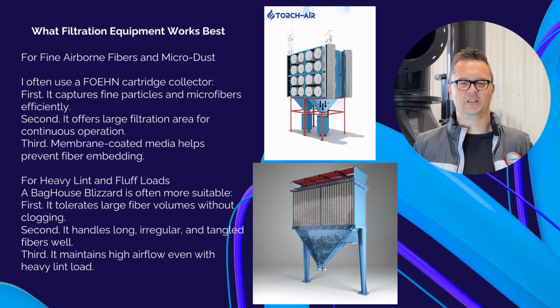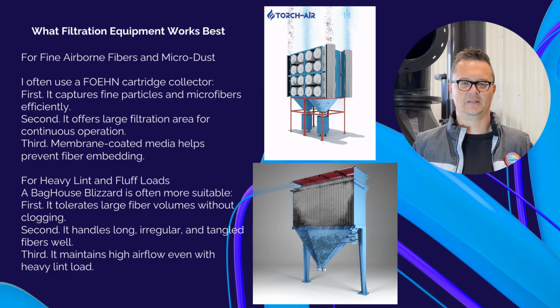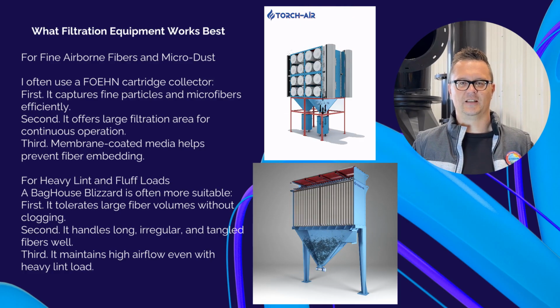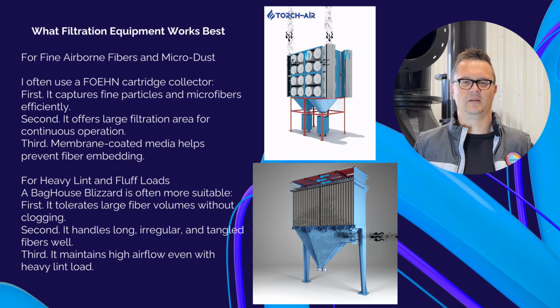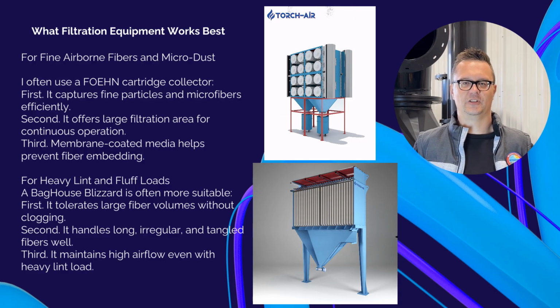For combustible textile dust, safety features must include: first, explosion vent panels sized for the collector. Second, anti-static filter media for synthetic fibers. Third, grounding and bonding across the system. Fourth, isolation valves in ducts to stop flame propagation. Fifth, optional spark detection for high-friction machines.